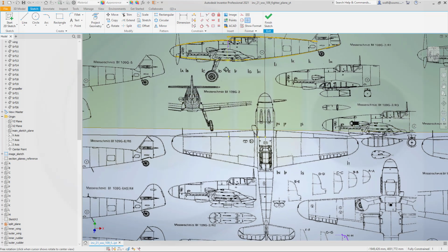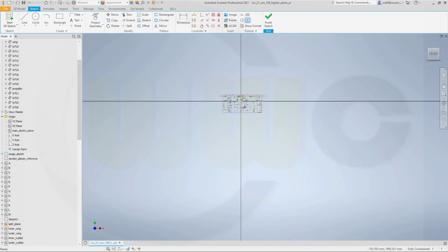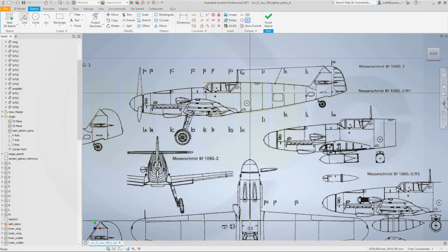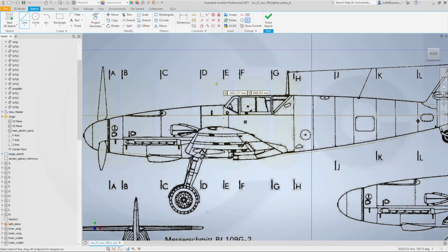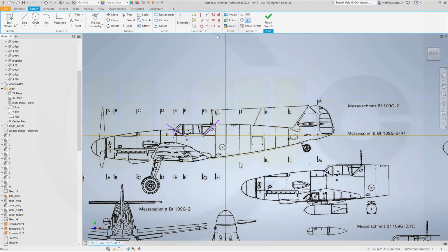Okay. Let's go for front view and zoom in. And that sketch might look something like. It should go from here to this position and there and then up. And this line should be aligned with that split plane. Where's that split plane? There it is. So go for collinear and put this line into that split plane.